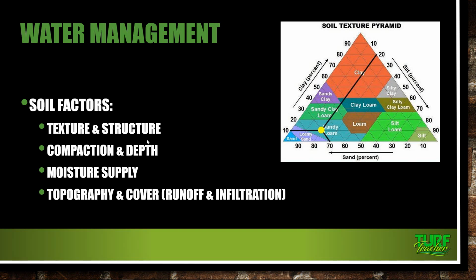And guys, it goes back all again to a site inventory and analysis. You should be doing soil tests for each one of your properties on a yearly basis. If not, definitely 2 years. But you get a new property and you take a soil test, and it's going to tell you the nutrients that you need to add, but it's not going to tell you what the texture or the structure is. I mean, you're going to have to get out there and take some core samples yourself or do the ribbon test and see what kind of soil that we have. And that's all part of doing the site inventory and doing the analysis for it.